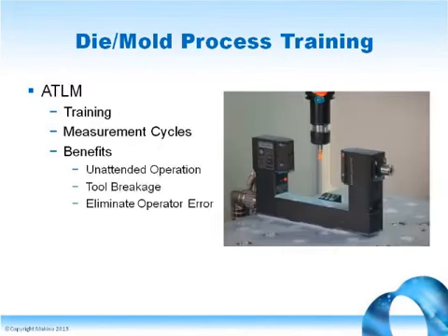ATLM, Automatic Tool Length Measurement. During the class, we will spend time on the machine training on how to use the ATLM in all of the measurement cycles. We will discuss the benefits of having an ATLM. We will show you how to utilize the ATLM in an unattended operation to check tool length and tool breakage before and after the program to help eliminate operator error.